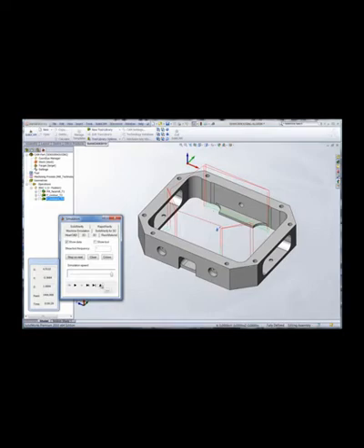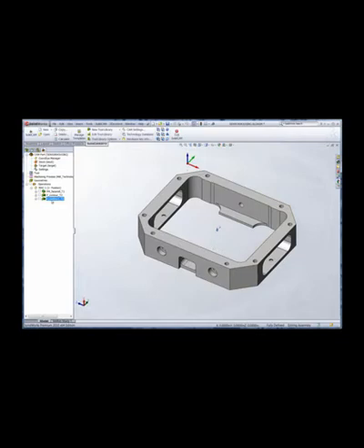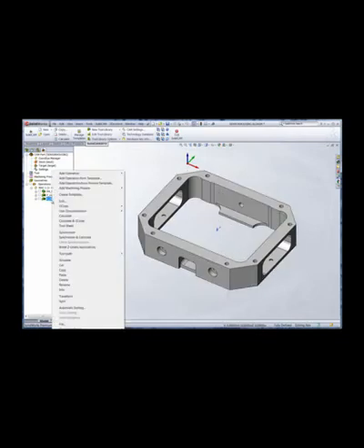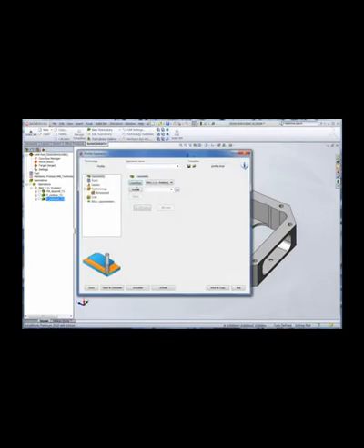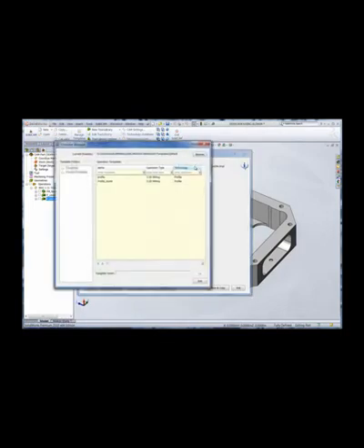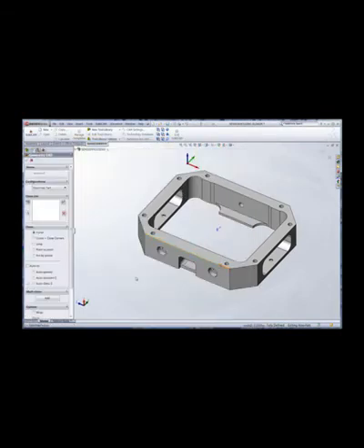Now this is maybe a little bit of a heavy toolpath, so we may want to add another pass. By using our clear offset, we can assign an offset of 125 thousandths and then assign the same for the step over. This will give us 2 tool paths at each of the pads, reducing the strain on the tool.